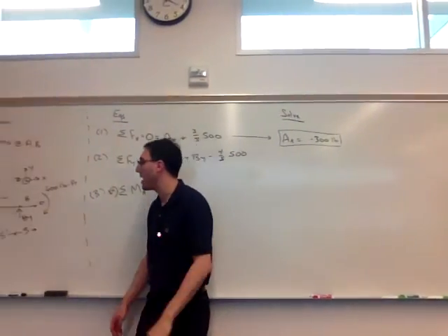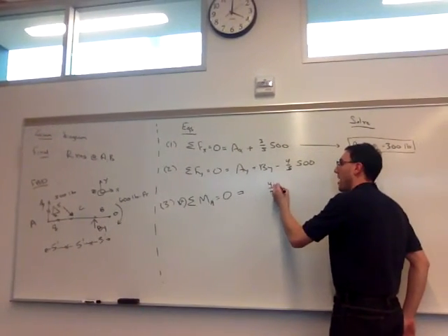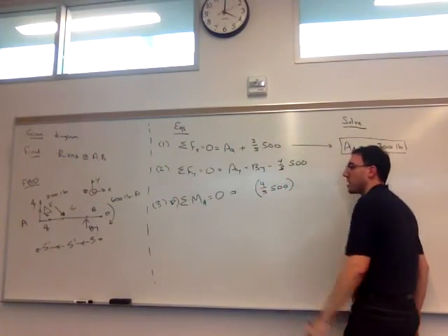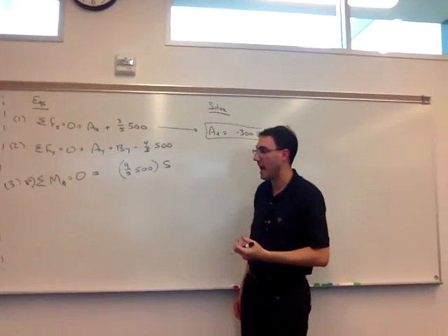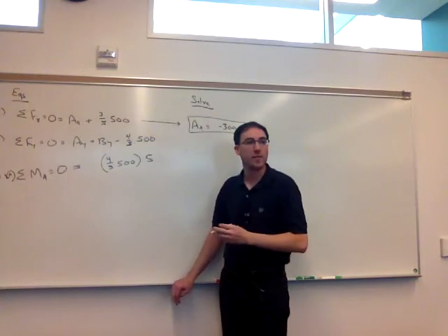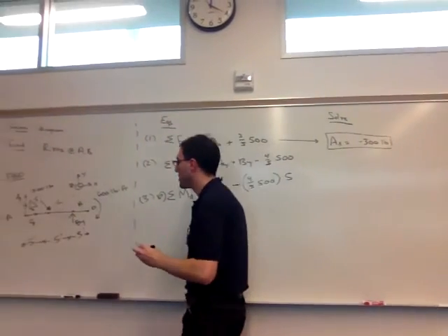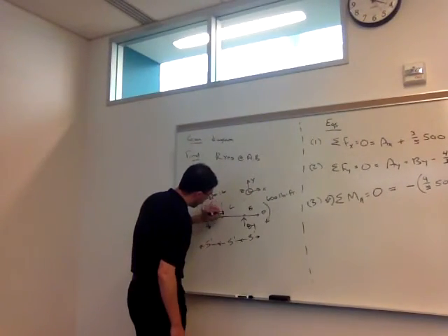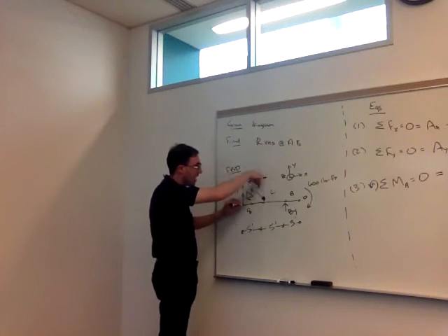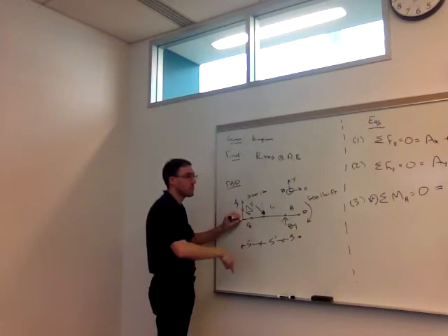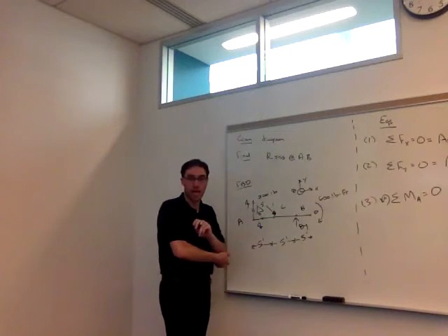All right, let's say one component at a time. So I heard the 4/5 part. So the vertical component of that applied load of 500 is the force, times 5 is its moment arm or its perpendicular distance to A. Is that positive or negative around A? So again, if we envision this pointing down here, holding at point A, if we push down here, the whole object would want to spin clockwise around A, making this a negative moment around point A.